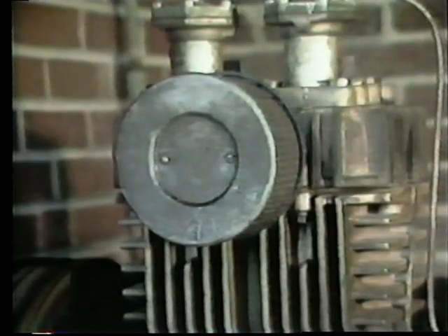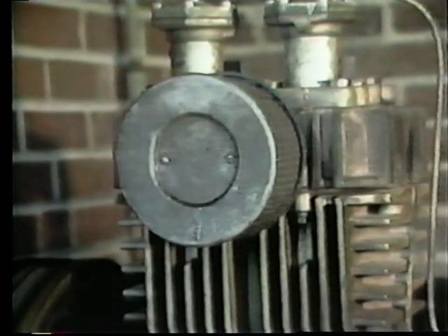You'll remember we stressed the importance of regular filter maintenance. First, as good as they are, filters cannot remove all the particles of dust or dirt that may be drawn into the compressor intake. And in most cases, any dirt or dust that gets pulled in gets pumped through to the discharge port.